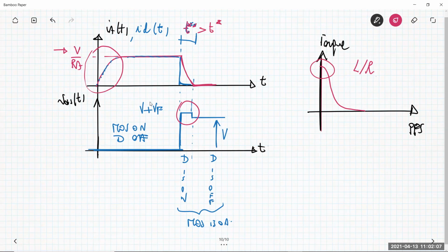The motor is typically chosen basically by looking at the torque capability, not just giving indication about the inductance. So you have one free parameter, which is the voltage V. If you want to increase the speed of the turn-on, you have to increase V. But if you increase V, you are also increasing the current here, and the current is not free to take very large values.